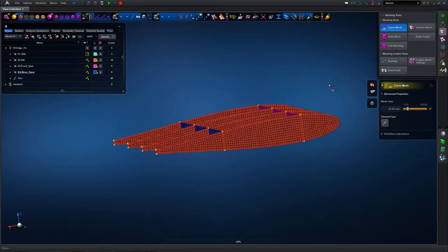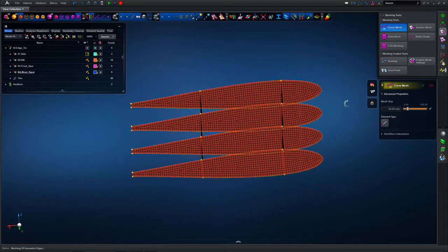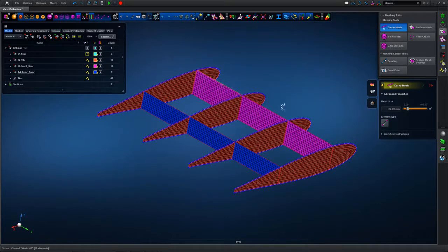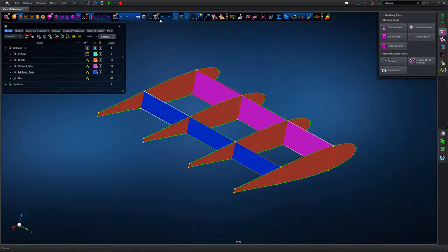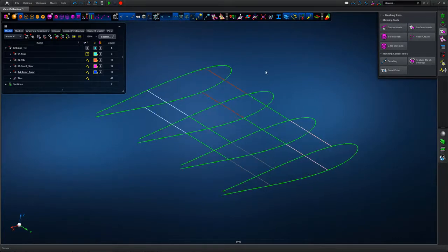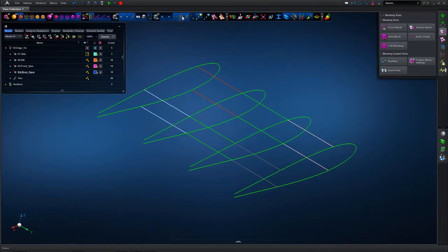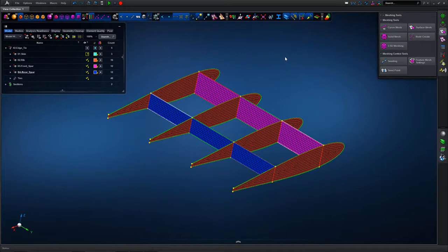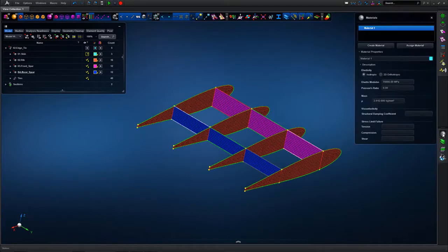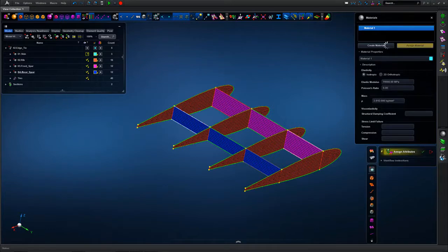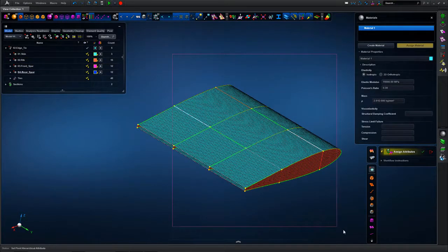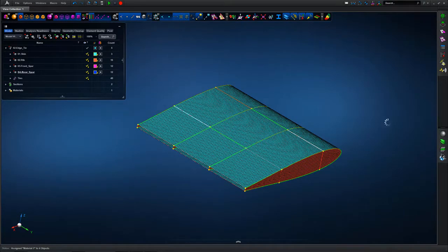Developing the model further, so this is a real-world example now where we might want to understand the load going through a given joint or a given region, maybe develop the free body loads across one of these discrete parts within the assembly. So we're going to introduce some one-dimensional beam and spar flanges. So we quickly mesh those regions, and we can see the bar element definitions. And now we need to define a section. Well, first of all, we're assigning a material. Now we've got all of the mesh 1D and 2D entities complete.